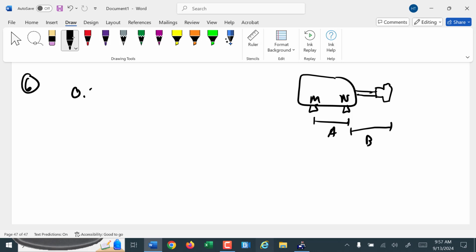So it's the 0.026 over the total distance is what we want here. When we're shimming the near foot, this becomes our pivot. So the distance from the pivot is just the point that stays in the same spot. So the distance we have to get is from that out to here. So that's going to be the 10 plus 16.